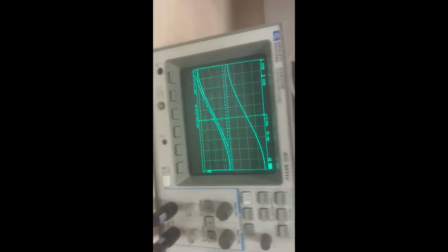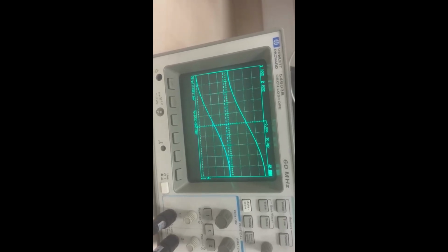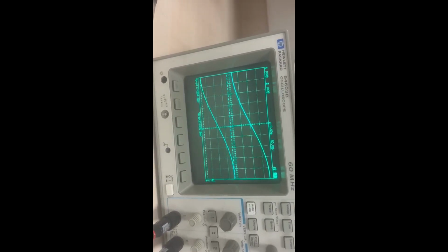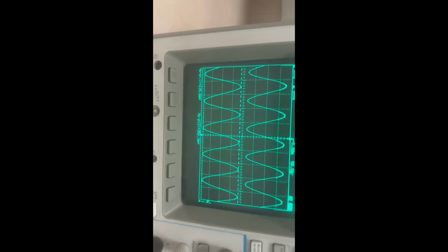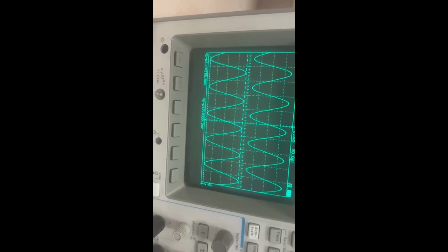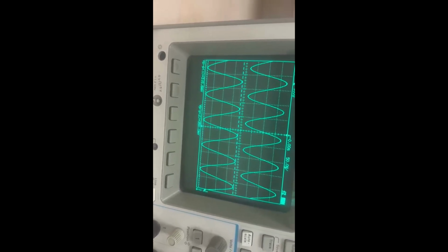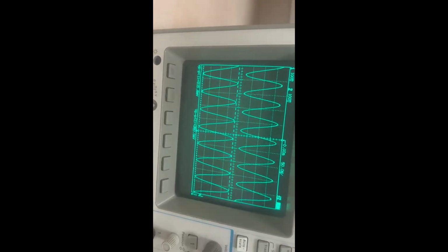In this part of the experiment, I focused on the frequency response of the circuit using a 100 ohm resistor. I started the experiment at a low frequency of 1 Hz and carefully observed both the input and output voltage signals on the oscilloscope. As I gradually increased the frequency, I meticulously recorded each value in the data table to map out the circuit's behavior.